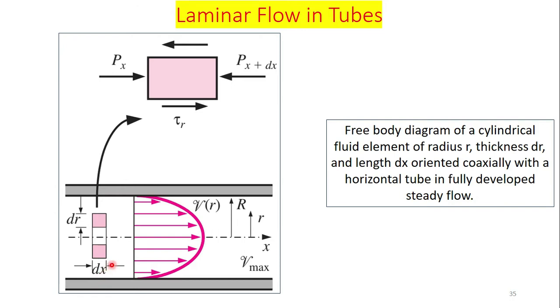The pressure force acting on this differential element is the product of the pressure multiplied by the surface area. Now we will use the same expression, the product of pressure multiplied by the surface area, to give us the force balance. Now we are going to apply a force balance on the volume element in the flow direction.